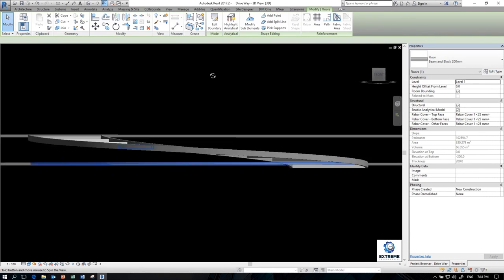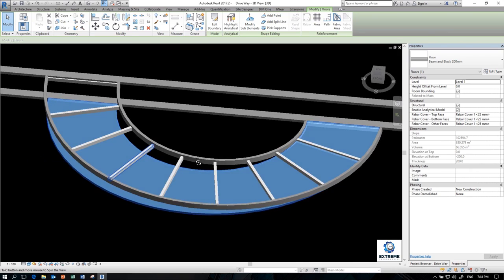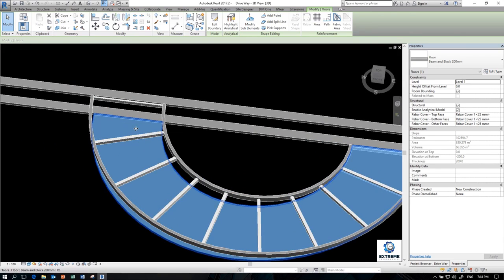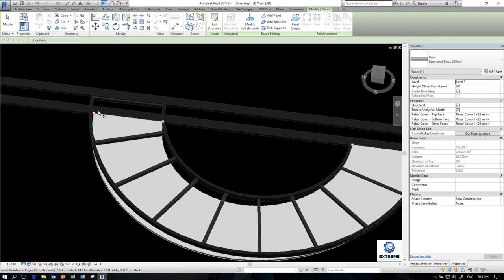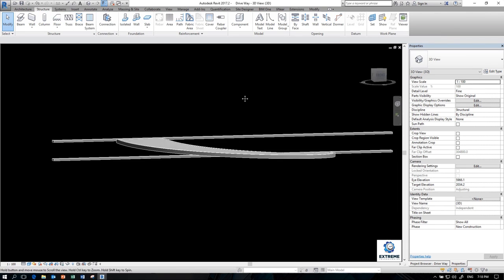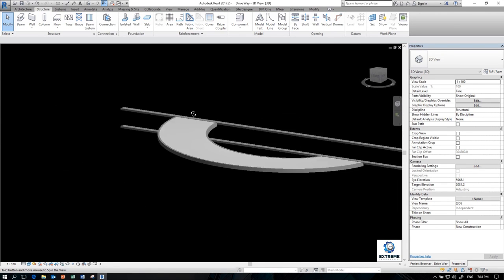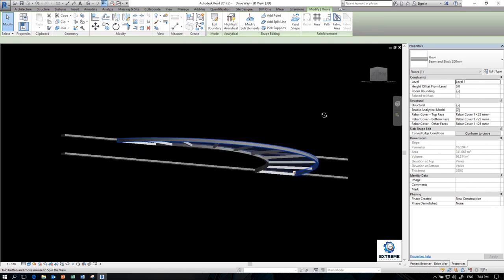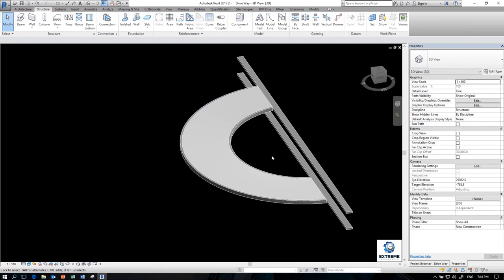Oops, what's this? Why does it happen? Because we draw the floor on a plane, so we are going to edit the points. We are going to do the shapes. So here's the command to change the elevation of the floor at this point. Select the floor, edit this one, select this line, change the elevation. It's 3 meters in this case. See how nice it is. Really cool, huh? See, no cross lines, very clean surface.